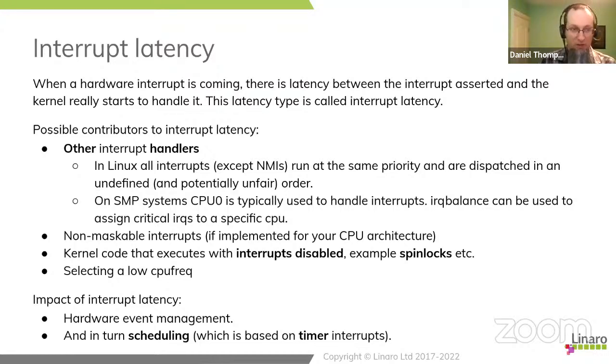The final thing that we should mention while we're talking about interrupt latency is that during interrupt handling, there is no opportunity to boost the CPU frequency. CPU frequency in modern systems is driven by the scheduler. Interrupts happen outside the supervision of the scheduler, and therefore, even if the interrupt load is high, the scheduler can't necessarily react and cause the CPU frequency to go up. So there's not really a great deal that can be done about that except making sure that the minimum CPU frequency you tolerate is sufficient to meet your real-time specification.